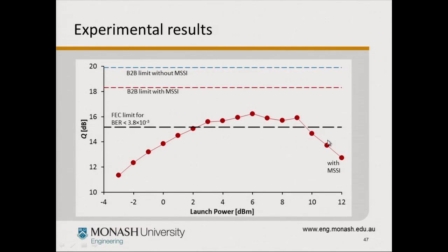And there's the performance for optical phase conjugation. So we see here, because the phase conjugation causes some power loss in the middle of the link, we see a small penalty on the noise side, but we can gain a very large amount on the nonlinear side. So at high powers, we can see the link is effectively compensating, with the second half compensating for the first half.